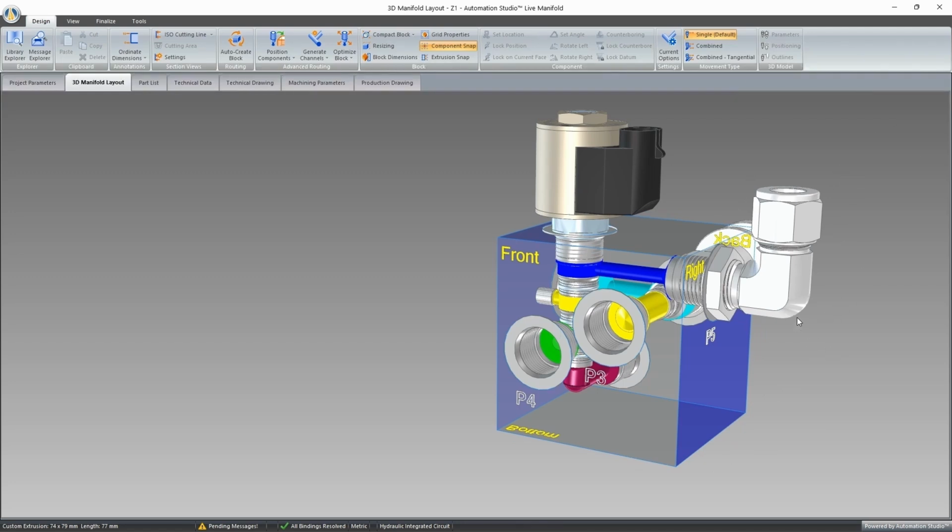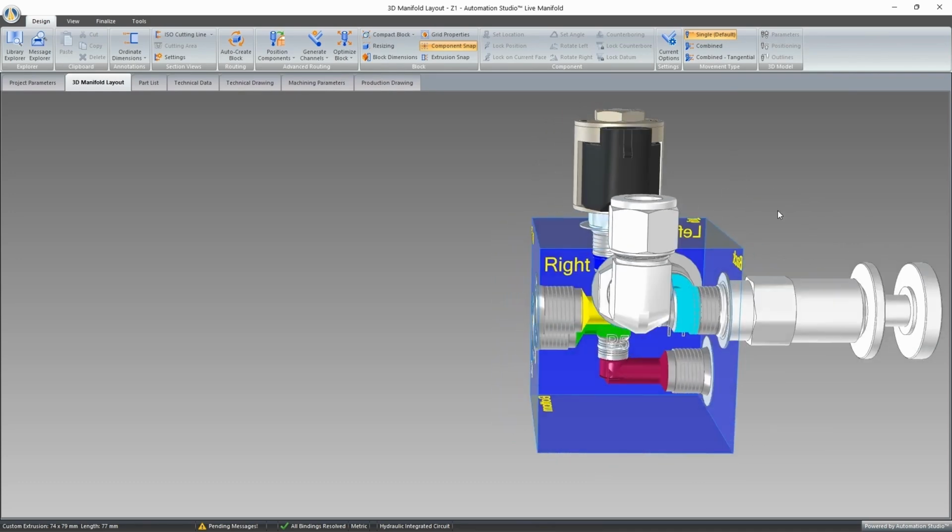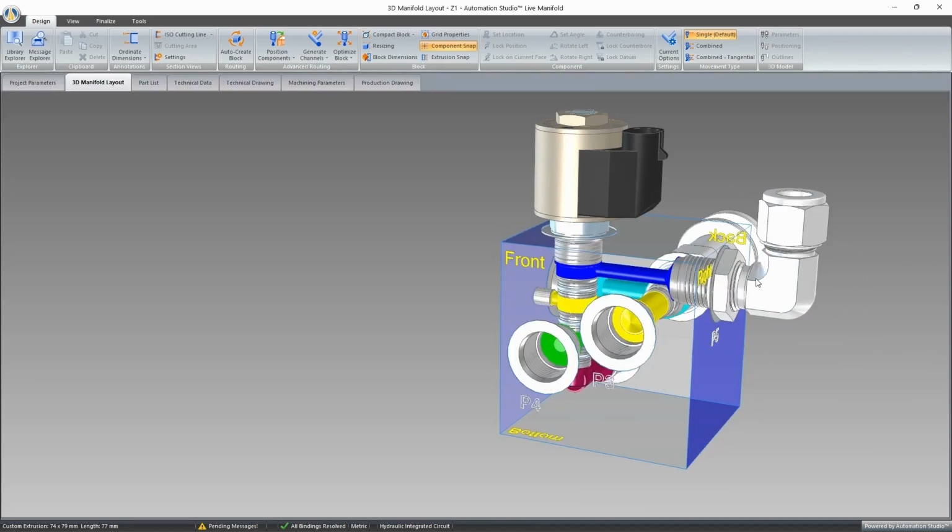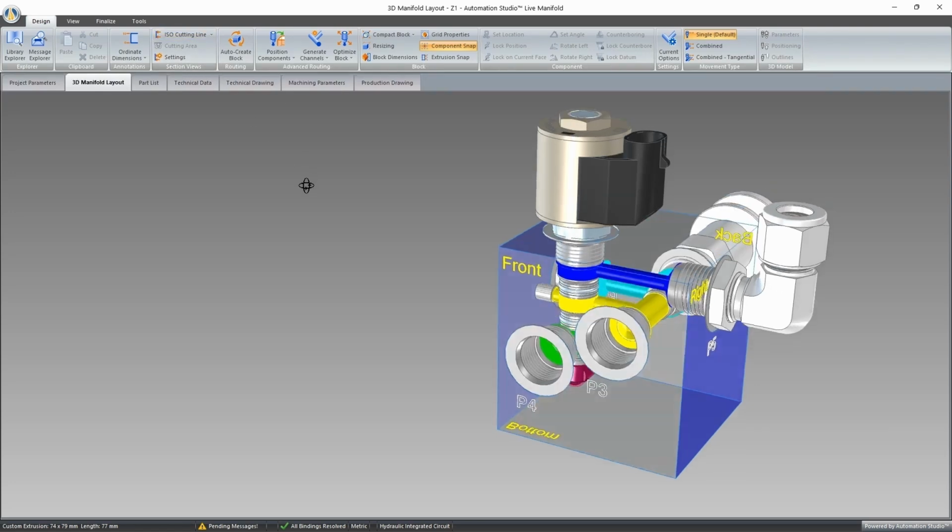So now I've showcased the generic use of step files to replace our generic 3D model or to add a 3D model to components like ports. The next thing we're going to want to take a look at, as a new feature, is the ability to add section views that we can use then in our technical drawing documents. So you may have noticed, in addition to this 3D model group of commands, we also have another new group of commands, which is the section views group.